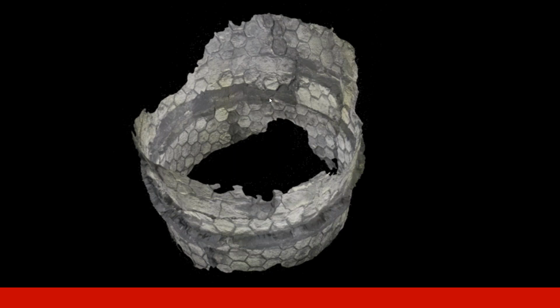And what we discovered is this kind of erosion, this pitting in between two layers of the stuff. And the question was, looking at the video, is this a problem, right? You need to know how deep the erosion is to figure out if it's going to make it to the next maintenance interval, to the next shutdown. And look, just flipping through the video frame by frame, it's pretty difficult to get a view of what exactly you're looking at. But just with this 3D model, it becomes obvious pretty instantly that it didn't go all the way through, and it was probably fine for another 2 years, which was the next scheduled maintenance.